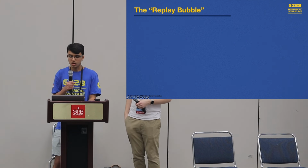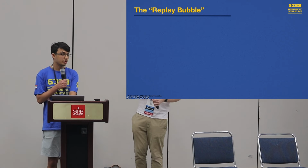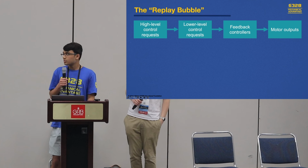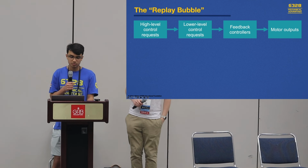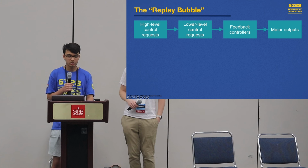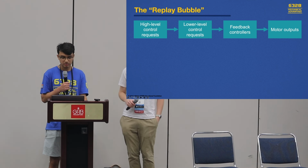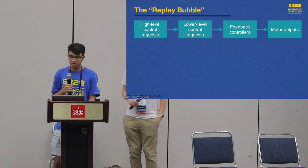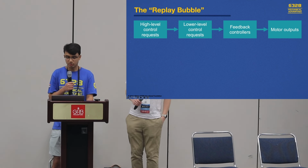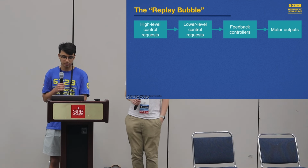There's lots of nuance with this concept, so let's take a further look. You're free to define the I/O interface however you want. Let's walk through an example. Most subsystems have a cascading set of controls. You have high-level control requests such as moving a swerve drive forward. Lower-level control requests can involve something like moving the first module at speed X. Feedback controllers such as position/velocity PID controllers, and motor outputs that produce outputs such as voltage or duty cycle.